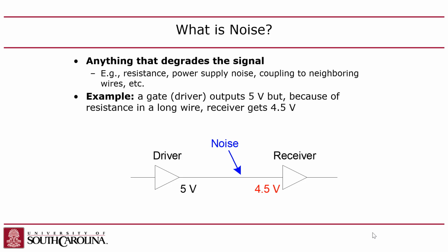Okay, so last time we were talking about CMOS logic, and I covered noise margins, which is the amount of noise you can tolerate on wires when you have noise affecting an already possibly noisy output from a driver gate, in order to avoid having the input go into the forbidden zone.